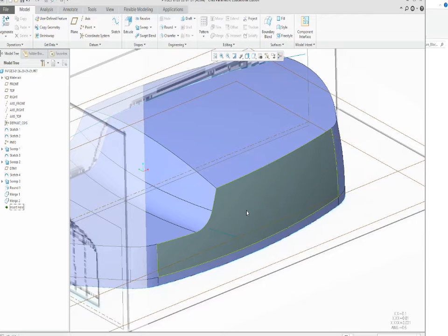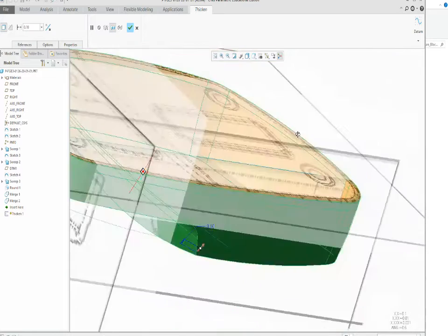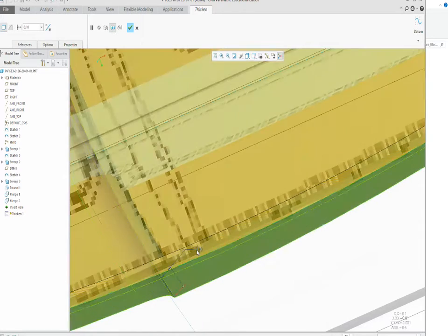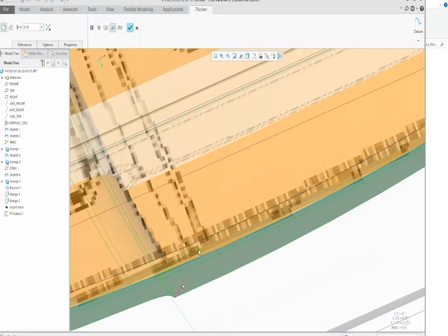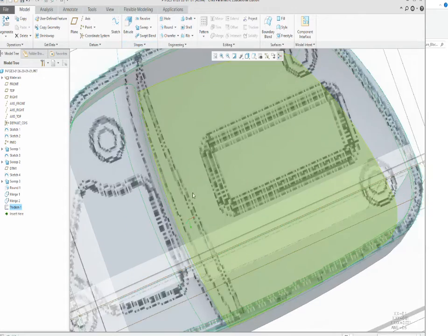for the offset. If we grab here and we do the thicken on the value, you can see how it's thickening on the inside, and it's telling us, okay, you're going to about 100 thou. Usually when it's guessing right here, it's right. So let's see. If we go back here and we go with 150, let's try that. And then we hit check on it, then it gives us 150.